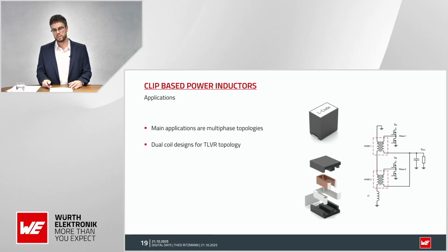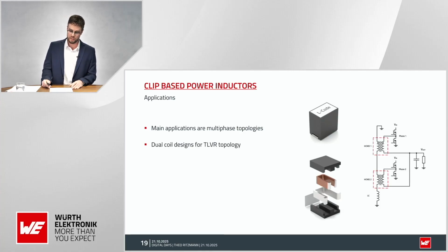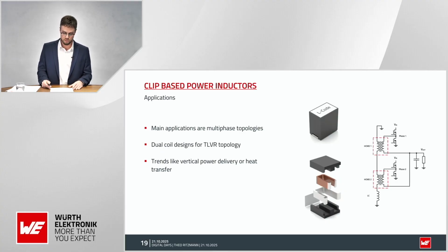Then these kinds of products are also used for the state-of-the-art TLVR application, which is also demanding the highest currents. And here, mainly dual coil designs are very popular, like shown on the right-hand side. Same as for the single coil solutions, these dual coil solutions are highly customized, because then they can also cover some extra challenges.